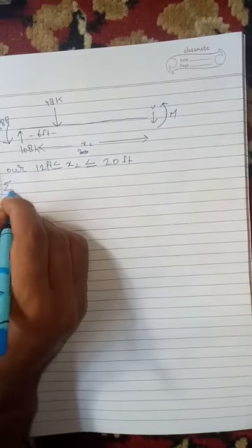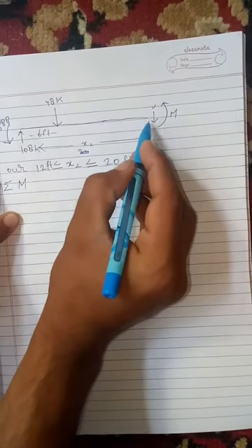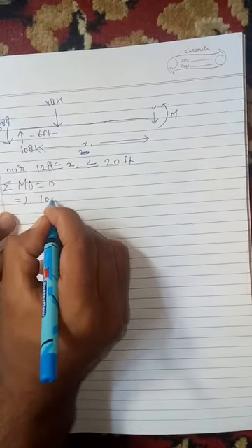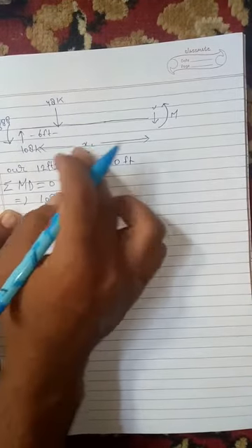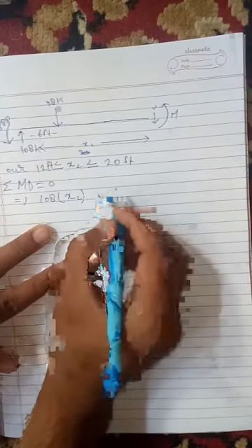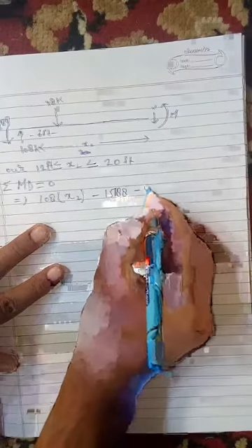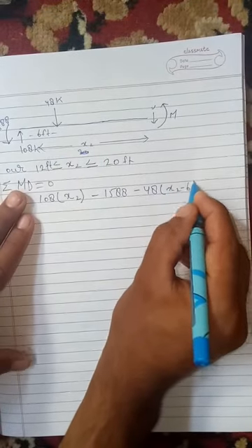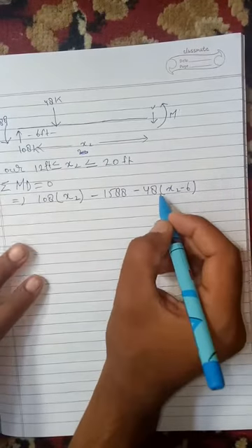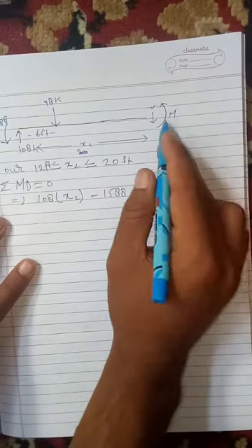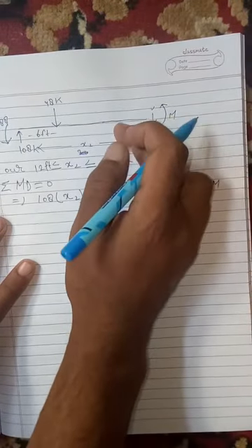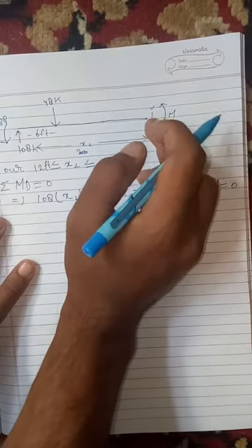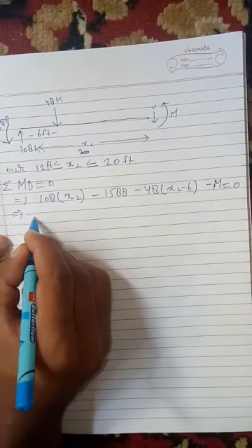So let's start. We will first use the equation summation of moment at a point. Let me take this point as D. Summation of moment at point D equals 0, which further implies 108, because this is trying to rotate the beam in the upward direction, that is why we take this as positive, into x2, minus 1588, minus 48 into distance. Distance is x2 minus 6 feet, x2 minus 6, minus M equals 0. Yes, moment M is also trying to rotate the beam in the downward direction, that is why this is negative. Minus M equals 0, and this force is passing through this point, so moment will be 0 due to this force, which further implies M equals